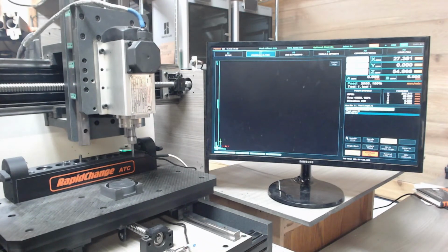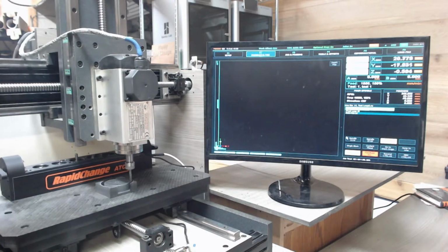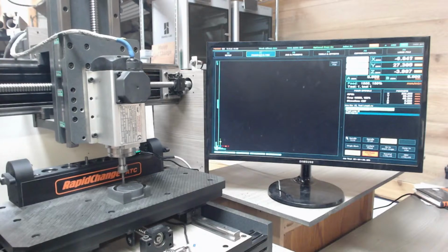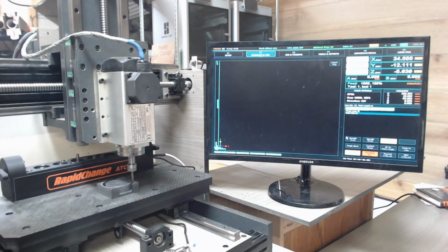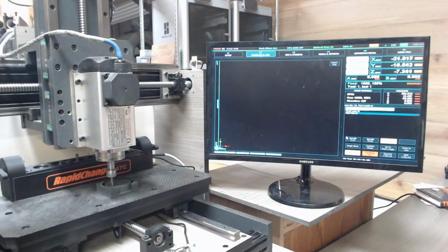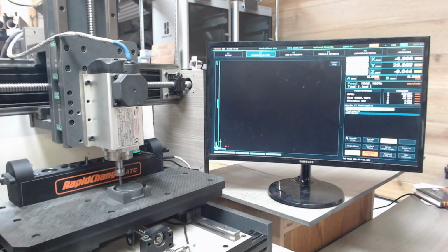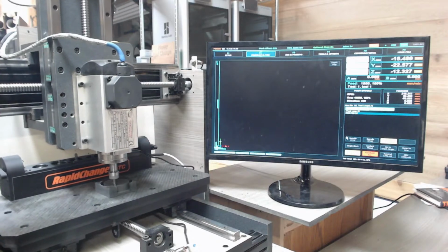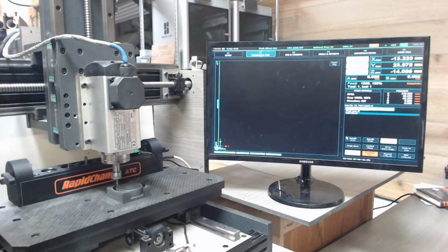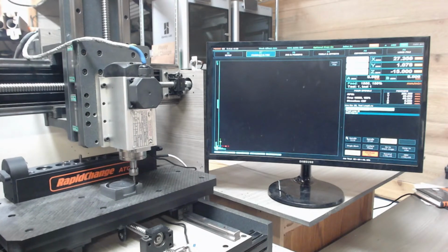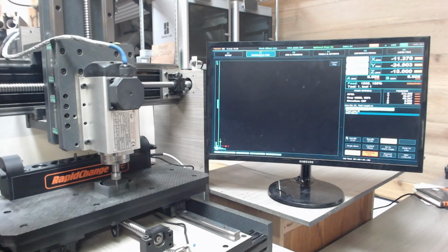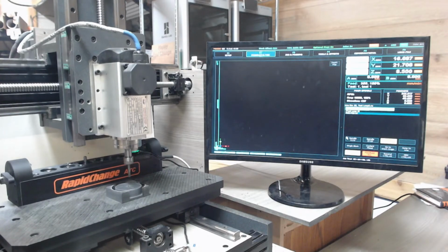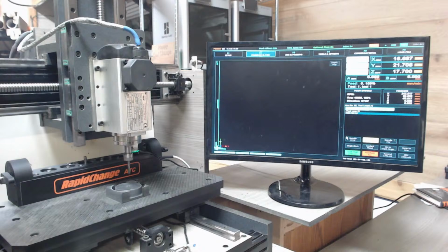So if you've got tool 1, if Masso thinks tool 1's in the spindle and you have to load it or start the file with it, it won't probe it. So between files, it has to either not have a tool in the controller brain or not have the tool that you're going to call.